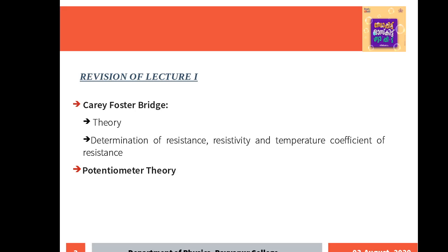We also find the same temperature coefficient of resistance using another relation, the equation for resistance at a different temperature in terms of alpha, that is, the resistance RT at any temperature. If you want the resistance at a different temperature, the change in resistance, RT minus R0, is proportional to R0, and also proportional to the change in temperature, T. So RT minus R0 is proportional to R0 into T, and if you put RT there, it becomes R0 plus R0.